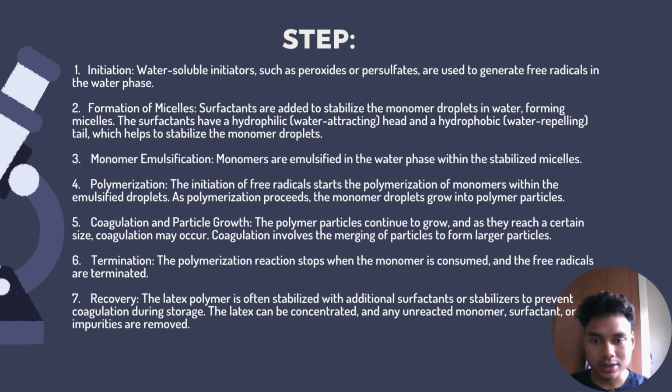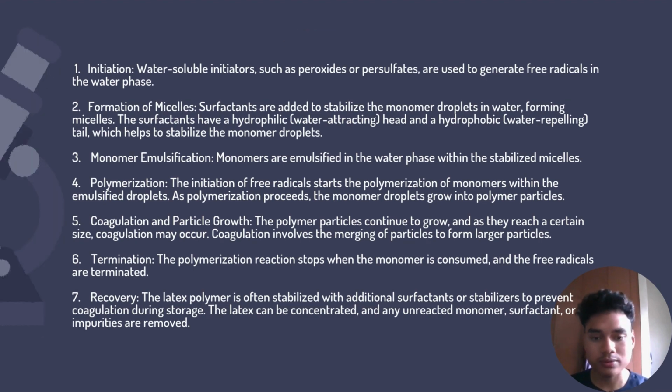Six, termination. The polymerization reaction stops when the monomer is consumed and the free radicals are terminated. Seventh, recovery. The latex polymer is often stabilized with additional surfactant or stabilizer to prevent coagulation during storage. The latex can be concentrated and any unreacted monomer, surfactant, or apparatus are removed.